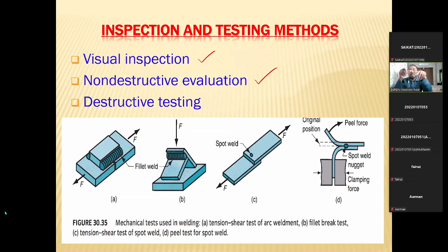We shall see if there is a pinhole, a gap, or a gas hole, and everything can be evaluated by using an X-ray, or by using sound. If I hit it and the sound is normal, that is okay. If the sound is not propagated normally, then we shall say there is some crack inside or something else. That is called non-destructive evaluation.